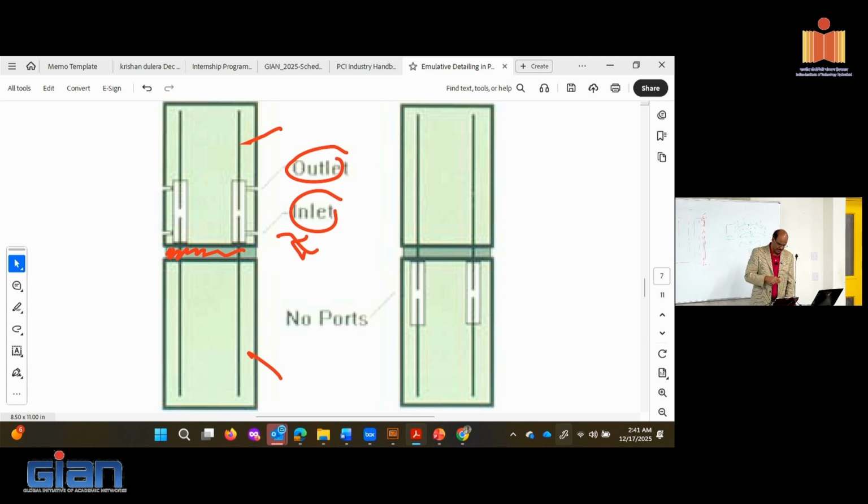So when I said on the first day that they will do all of the connections after they erect the entire building, this coupling, this grouting and everything happens after the full assembly of the entire structure, typically. I don't know if that's what you guys do here. Like when you do the connections, do you do it as the building goes up or do you come back at the end and do the grouting? No, sir. As and when it goes, we will do the grouting, okay. So in the US, typically they complete the structure and then...